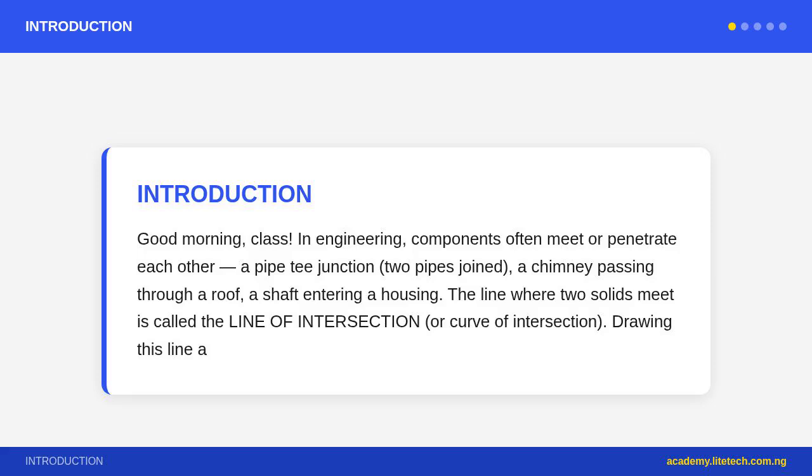The line of intersection is the locus of all points that lie on both solids simultaneously. Finding the intersection, general method. Step 1. In one view, identify where the surfaces of the two solids meet. Step 2. Use cutting planes and auxiliary planes to cut through both solids at several positions. At each cutting plane, find the resulting lines on each solid surface.